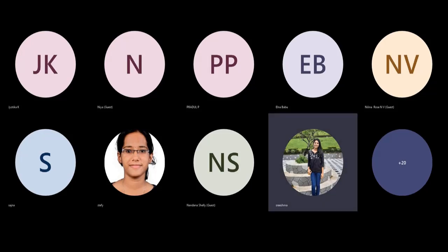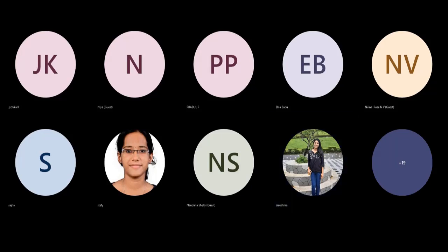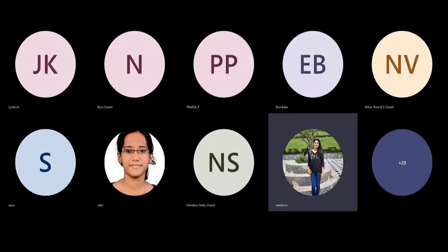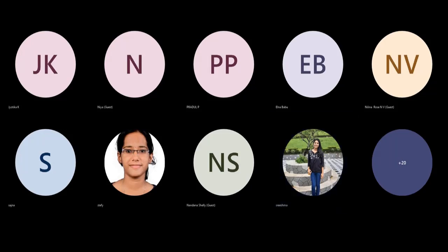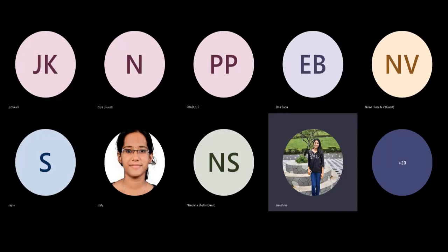Now, another factor which is really important when we detail or design a column is its L by D ratio. L by D ratio is an essential factor to consider when designing a column because it affects its ability to resist buckling. Buckling is a failure mode that occurs when a slender column is subjected to compressive load, causing it to deflect laterally. The buckling load of a column decreases as its L by D ratio increases.